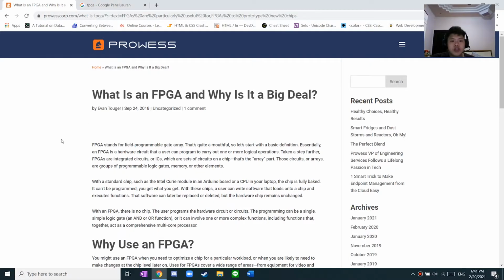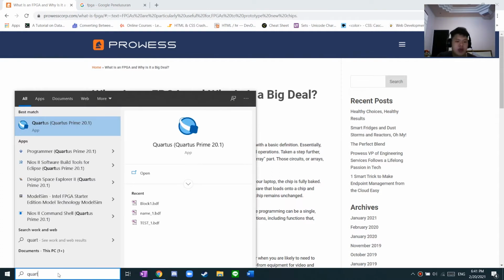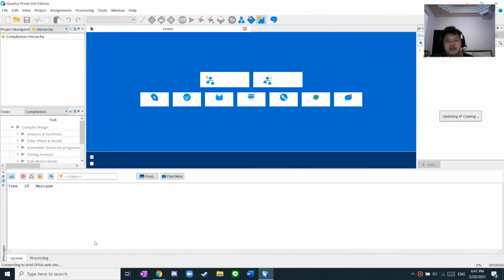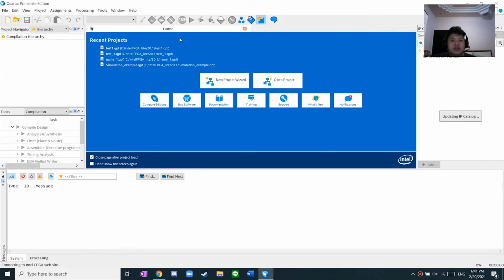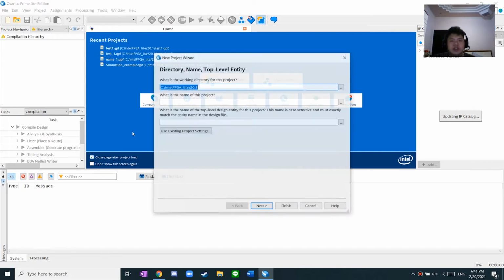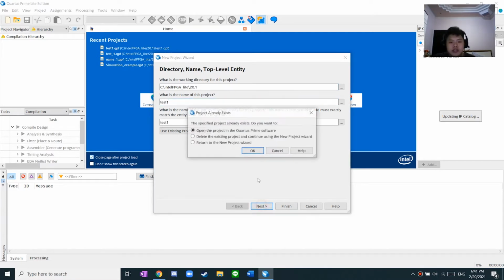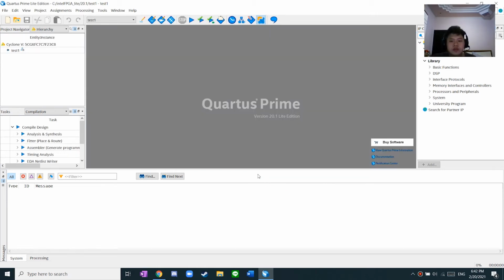In this second part of the video, I'm going to explain how I run a simulation in Quartus by Intel. So what I'm going to do is open the application. If you don't have it, you can install it and search for a reference. It's quite simple. When this pops up here, just choose New Project Wizard and name it whatever you want. I'm going to name it test one and just click next. Open the project, and just wait for a moment. When this shows up, it means that the project you created has been established.